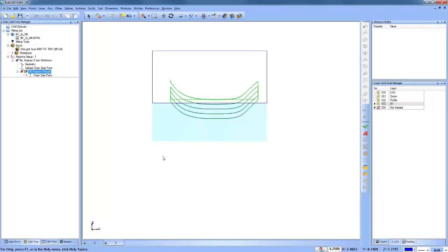You can just choose update all geometry and recompute. This applies when you've already programmed the job and then you're either changing a zero or some aspect of your toolpath. You can do an update all geometry, and what it does is reselect all the toolpath in the background so you can recompute, versus having to go through each feature and do that yourself. Does that make sense, James?